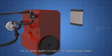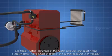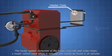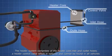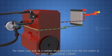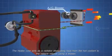The car heater system is a part of the engine cooling system. The heater system comprises the heater core, inlet and outlet hoses, and a heater control valve which is optional and cannot be found in all vehicles. The heater core acts as a radiator, dissipating heat from the hot coolant to the vehicle.